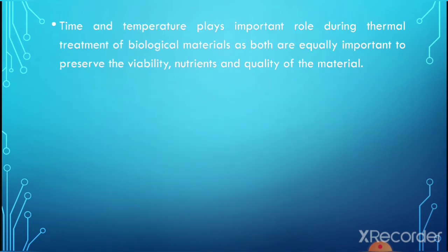Time and temperature play an important role during thermal treatment of biological material as both are equally important to preserve the viability, nutrients and quality of the material. For example, in pasteurization and sterilization process of milk, time and temperature combination plays an important role. Such as in pasteurization process of milk, every particle of milk is heated at a temperature of 63 degrees Celsius for the time period of 15 to 30 minutes.